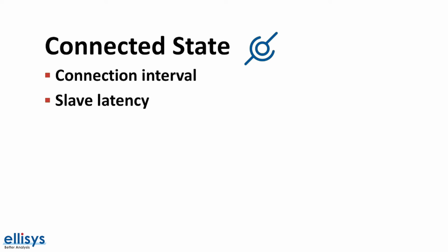Now, keep in mind that this value only defines the maximum number of connection events that the slave can skip, so the slave can still wake up at each of the connection events to send and receive data from the master if that's necessary. The bigger the size of the characteristic being read or written, the longer the radio stays on, causing an increase in current draw. So keep in mind that having a characteristic that is optimized in size can help in reducing power consumption.